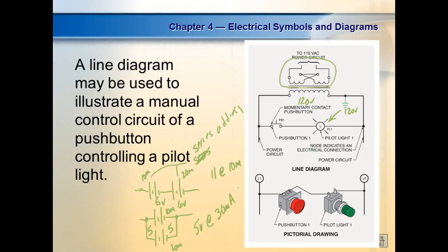Okay. So over here, we're going to deal with turn ratio. Right now we have these coils up there hooked in series. Can y'all see? So here comes the transformer. And this would be 2 of our power lines. In a 3-phase system, they stagger the transformers between L1, L2, then L2, L3, then L1, L3. It doesn't make any difference, but they don't put all their transformers on one phase. Their ultimate goal is to balance the phases.